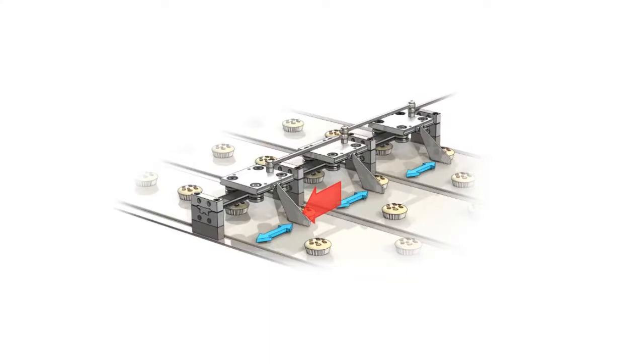We must also consider the force applied as the cake and paddle make contact. The force applied is a result of the coefficient of friction and the weight of the cake. This is 5 newtons, and it occurs at a distance of 120 mm from the centre of the carriage, but also 80 mm below the carriage.